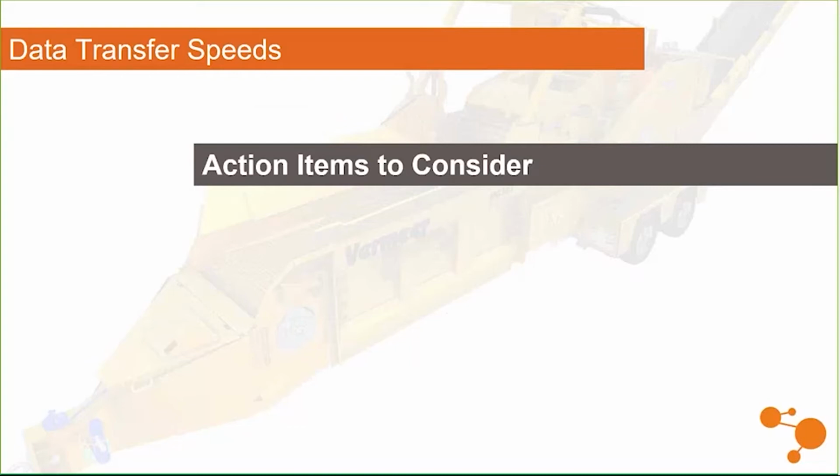So this is one of the easiest things to test in your organization. If you're diagnosing whether your network is bogging you down with your large assemblies, pack and go an entire large assembly, put it on your local C drive, and open it, and see if you get an acceptable gain in time by doing nothing else but that. I highly recommend trying that out if you aren't already.